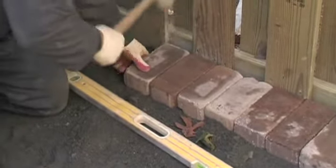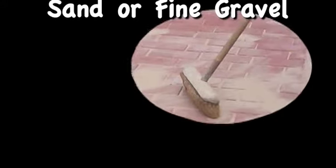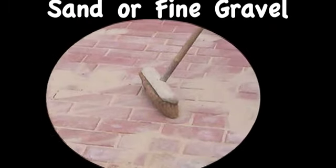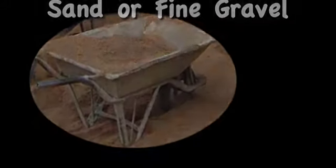Pack the pavers close together for greater stability. The next step is to cover the pavers with a thin layer of sand and sweep the sand into all of the spaces separating the pavers. Continue adding sand and sweeping until all of the spaces are filled and even with the top of the pavers.